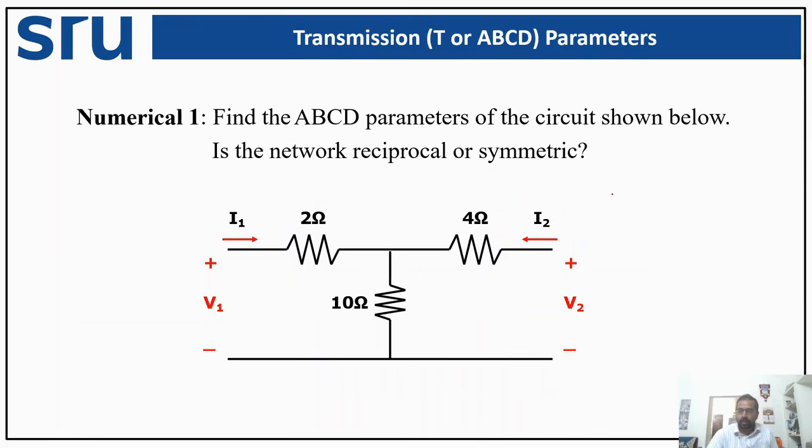We are going to have a resistor over here, and as I2 is equal to 0, no current flows through it. So the complete current goes to the 10 ohm resistor. This is my 10 ohm, and this is my 2 ohm. This is the voltage V1 across these two terminals, and this is the I1 current entering the first port positive terminal.